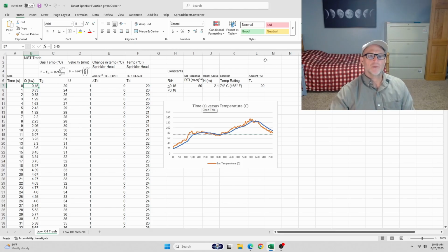In this particular example, there's wide variability in what you can assign, but there are different ratings for temperatures on the sprinkler head. A lot of the standard response heads are on the order of 165 degrees Fahrenheit. Typically in industrial applications, for standard response heads, it's what's called a eutectic metal. It's basically a solder of sorts. It's not necessarily tin lead, but when that mass, that eutectic metal, absorbs energy so that the metal itself is 165 degrees Fahrenheit, it no longer has enough force to resist the pressure of the water, and that head opens up. So that's the principle behind it.